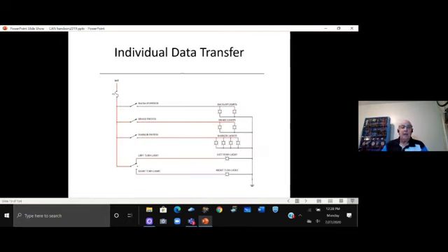All right. In this process of explaining CAN Bus to a student, I always start with individual data transfer. And what do we mean by that? Well, it's maybe a little bit of a bastardization of data, but what happens when we turn on the backup light switch? When you close the backup light switch, the backup lights go on. Why? Because they have a ground on one side and they now have power from F1 on the other side. Same thing with the brakes, same thing with the markers. And we have a multifunction switch. This is a very, very simple diagram, and it's obviously missing some things.